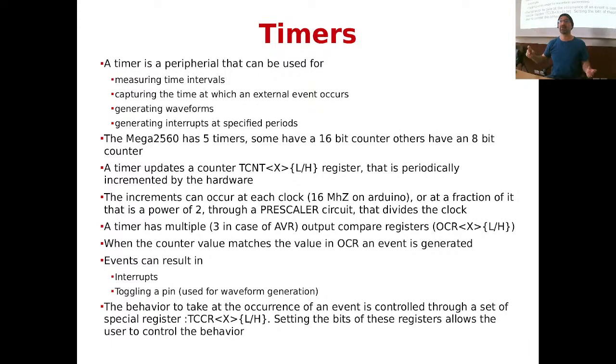Each timer is characterized by this most important thing, which is a register that counts. This register is accessible as a variable in C++ or in C, and it's referred to as count, timer count x, where x is 0, 1, 2, 3, 4, whatever. Okay?